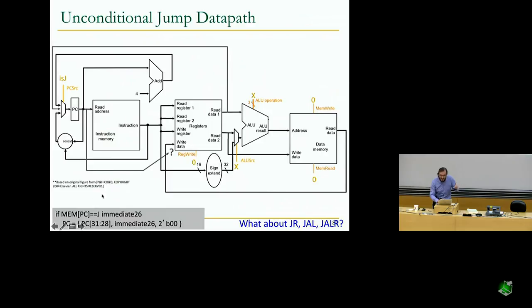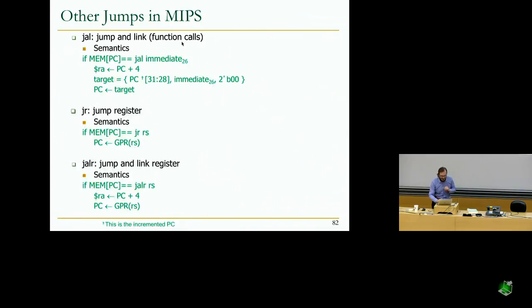So this is actually a wrong data path connection. It's actually done specifically this way. You should really save the PC to a destination register in jump and link, but the PC should really come from here. So you should be very careful when you're obeying the specification of the ISA, right? You should do the right connections in your data path, and of course you should set your control signals correctly to execute the instructions in a way that is expected by the programmer, which is the ISA. So this is for your information.